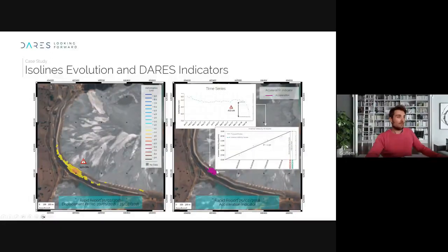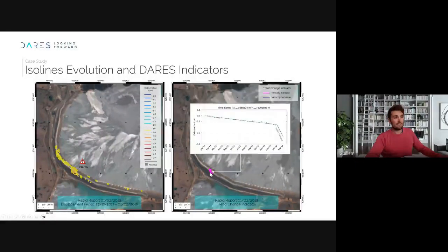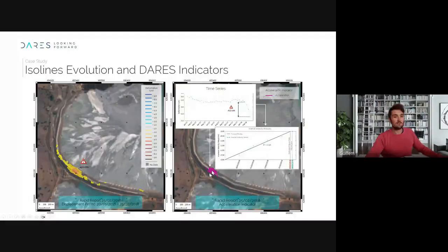And then 24 days later, the displacement was even bigger, and the velocity was not only increasing but accelerating. So instead of placing increase of velocity, you can point out acceleration. So here you are saying, this area is not only increasing in velocity, but it's accelerating. And you perform this inverse velocity analysis that gives you a first approach. That's what we do with InSAR.